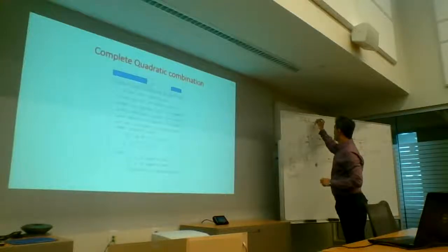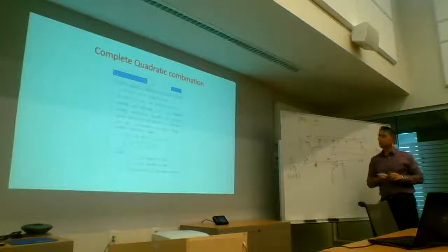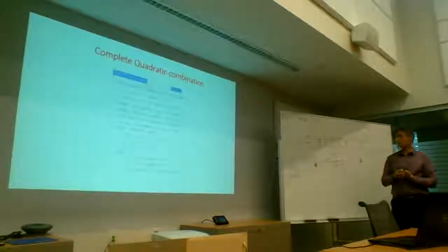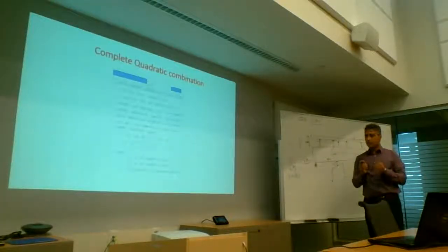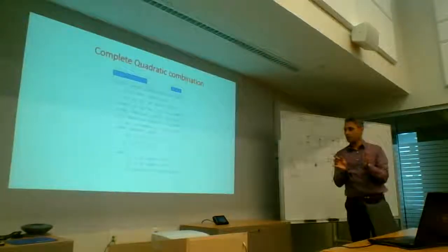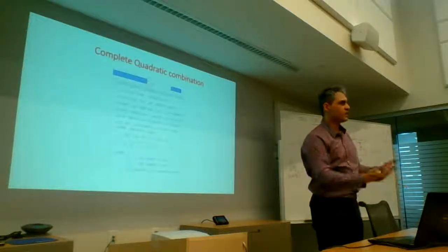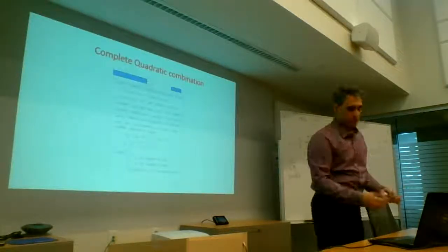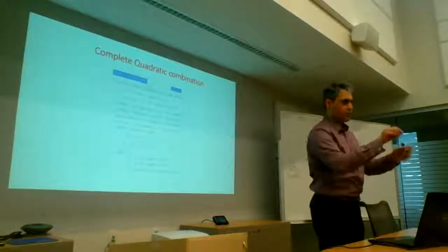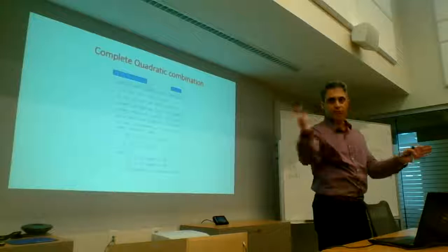Or you can use the CQC. I encourage people to use the CQC. So SRSS is good if your frequencies are well separated. Okay, so CQC pretty much works every time, given the problem we're trying to solve. It's still statistical, right? It's not time history where you're adding the responses at the same time interval. You're still looking at maxima.